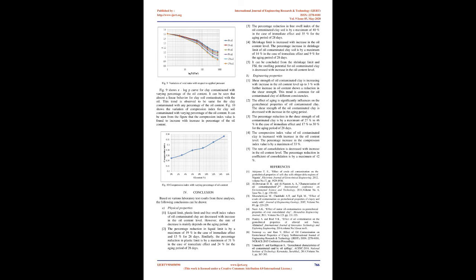Fig. 6 shows a decrease in the shear strength with increase in the oil content up to 3% for clay with medium consistency. The shear strength of clay contaminated with 3% of the oil content is almost equal to the virgin soil, and the shear strength decreased with further increase in the oil content up to 15%. The immediate response and the response at the end of 7 and 14 days show a small increase in the shear strength, but there is a considerable increase in the shear strength in the case of the soil samples tested after 28 days. Fig. 7 shows shear strength of oil-contaminated soft clay with respect to aging period.